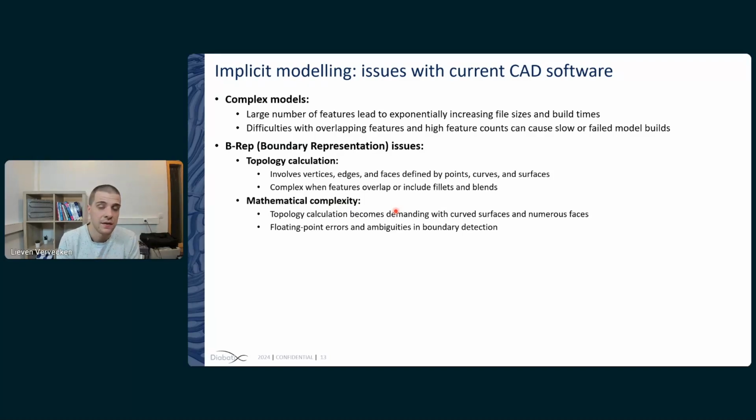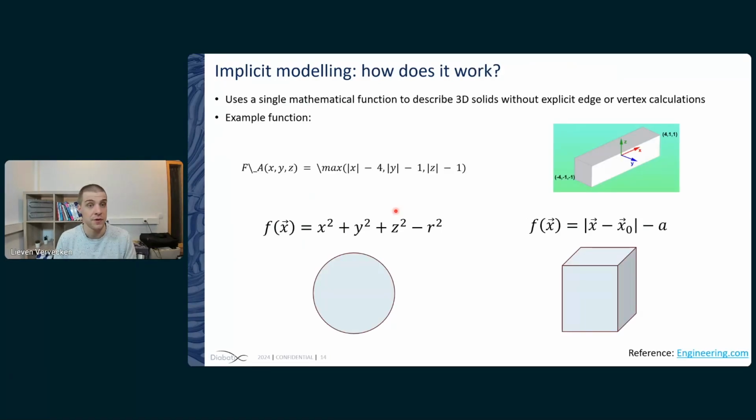If you want a very high resolution to easily capture all of those details, you need a very large mesh count and a very large number of facets. And the more facets or triangles you include, the easier it is for an error to sneak in. But this can be prevented by using implicit modeling, where your complex geometry is represented by a simple, or relatively simple, equation.